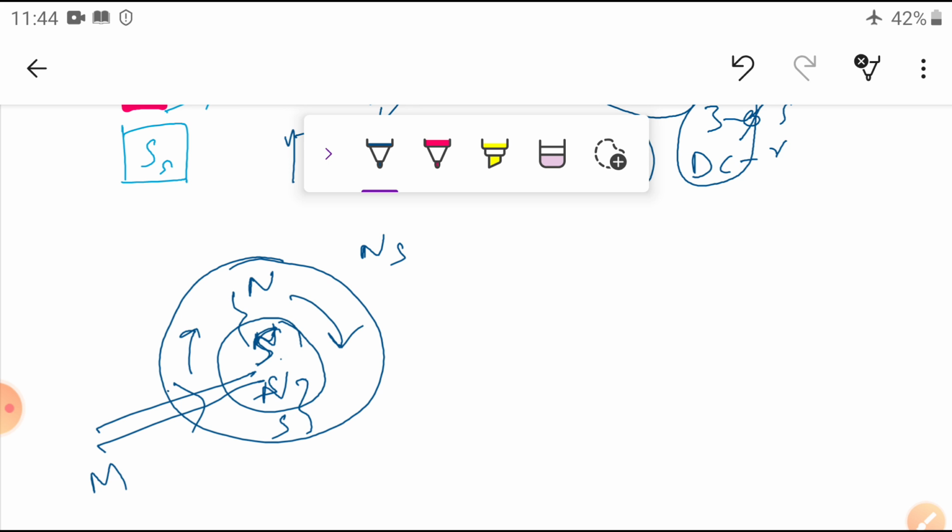Once it is rotated, the rotor is driven with the help of another external motor which has a speed higher than the synchronous speed. That means the number of poles of this incoming motor should be less than the synchronous machine poles, hence the speed is more. Once the mechanical input is given, the rotor also rotates at the speed of the rotating magnetic field.